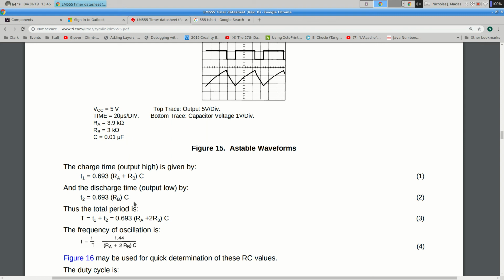You have parts going by on a conveyor belt. You have a light beam. And when the part goes by, it breaks the beam, and you use that to generate a little pulse. And you feed that into this missing pulse detector. And if there's a part that's not on the conveyor belt where it should be, this device will put out a 1, and it lights up a light or sounds an alarm. You go over and you know there's something missing from the conveyor belt right there.